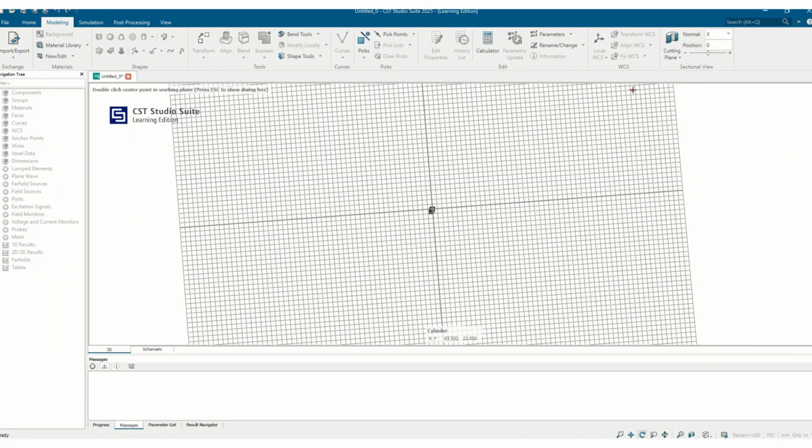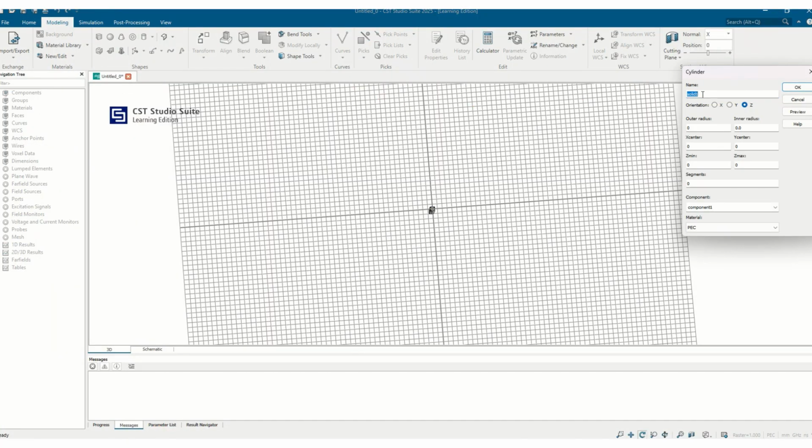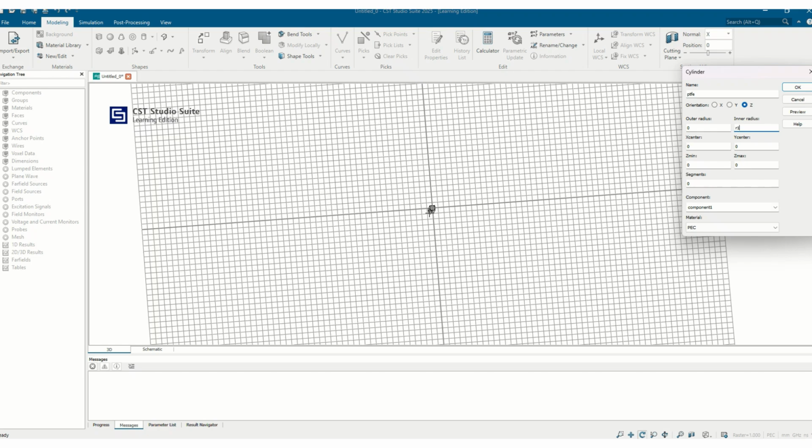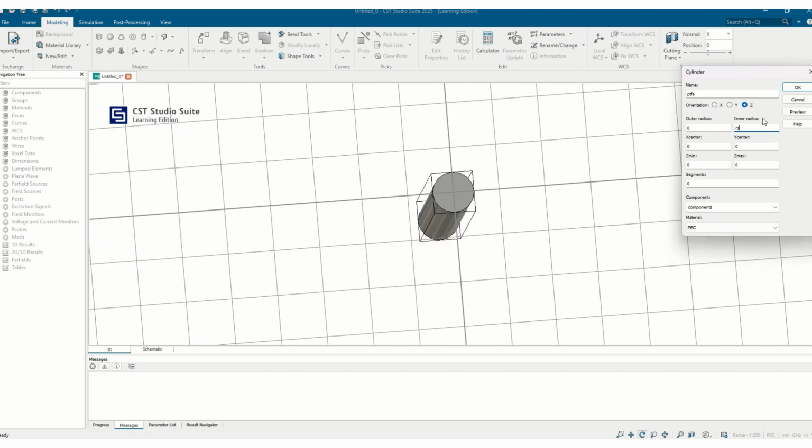Next, we can draw the dielectric. So this is made up of PTFE. So here the inner radius is because it has to come from this inner conductor to the outer layer. That is why inner radius is R1 and outer radius is R2. So based on our analysis, R2 is 1.5 and this one also you can give as H min to H maximum,